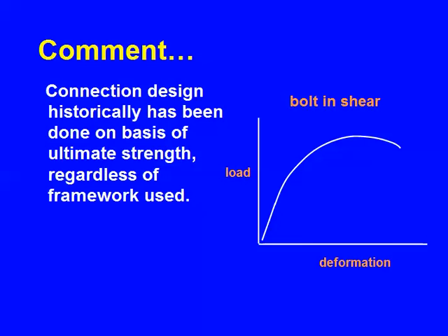But I want to reinforce the idea that connection design always was done, whether you're an allowable stress person from the 70s, and there are some people here who were, or you never got taught that way and you just got taught using LRFD. The basis for the design rule, trust me, was always the ultimate strength. And here's what happens for a bolt in shear. I'm going to show this in more detail in due course. Do you see a yield point?